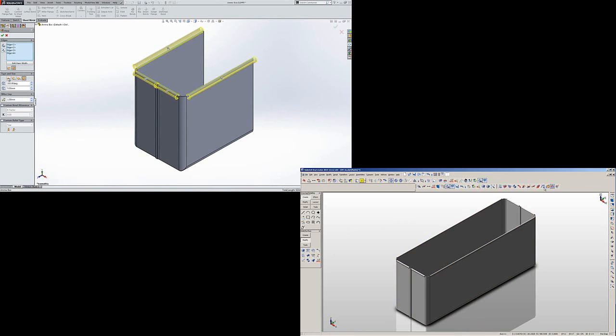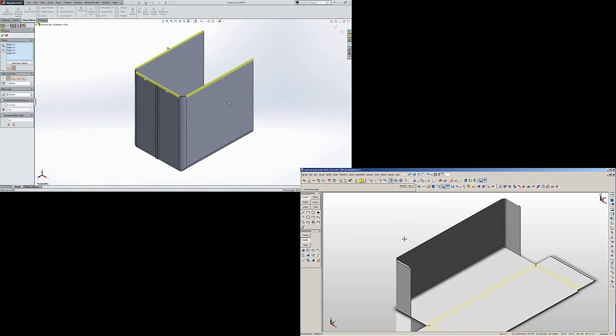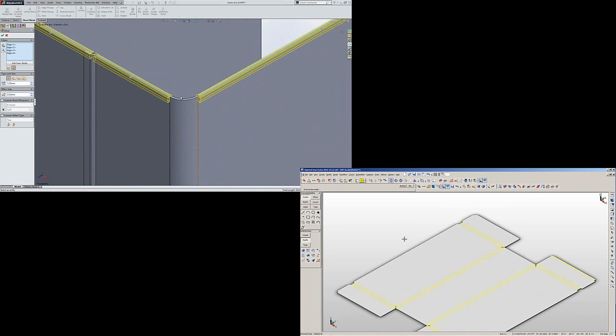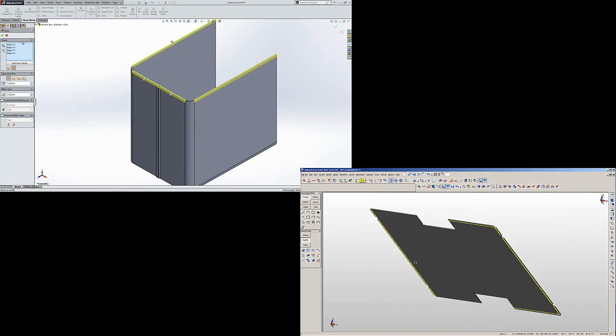We'll fill out the parameters of what we want. We want a 5 mil distance like so, with a miter gap of 0.1 as tight as possible, although there is no miters where these join because of the round bend here. So with that done, we can OK that.